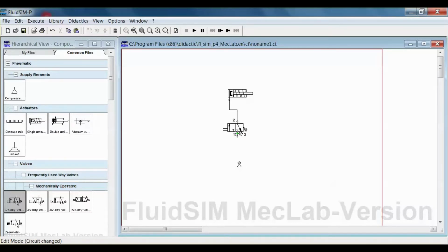to make to, and you can see the target came up with another green dot indicating you can create that connection there. As you see, if I move over to the vent, which nothing should be connected to other than the vent, there is a circle with a cross through it saying stop. So you can see where you can create your connections. You can connect to that line, but there wouldn't be any reason why you would need to. But as you can see there, I can make a clean connection, and that's the correct connection that I need to make.